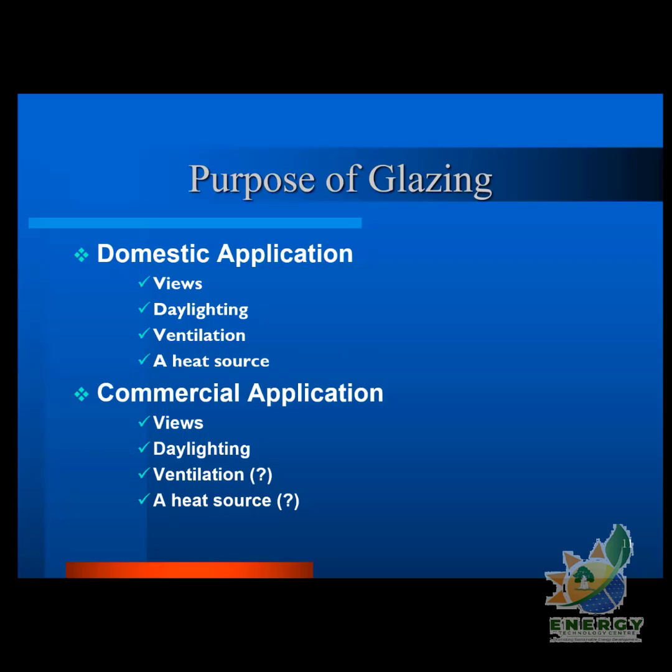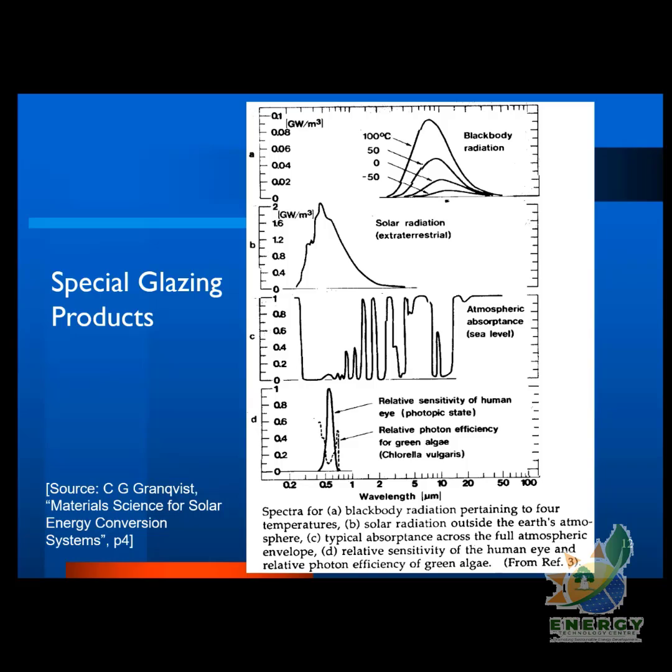This is where it's very, very important for us in Ghana to take these things into consideration in the design of our windows, especially with the new glazing systems that are being used around. Now, glass allows what we call shortwave radiation to enter, and then when the radiation enters and hits any part of the room or of the house, much of it is converted into long wave radiation.